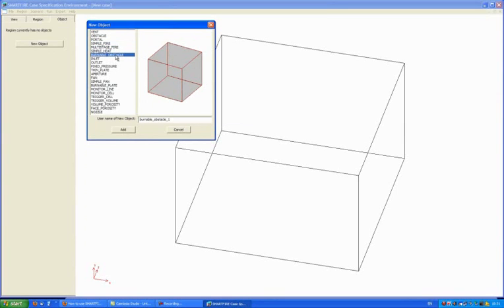Burnable obstacle is a different type of fire where the surface is allowed to burn and flame spread is allowed to travel over the surface. An inlet is a momentum source defined by velocities. An outlet is an area where flow can leave the domain, as is a fixed pressure, although slightly differently defined by a pressure value instead.